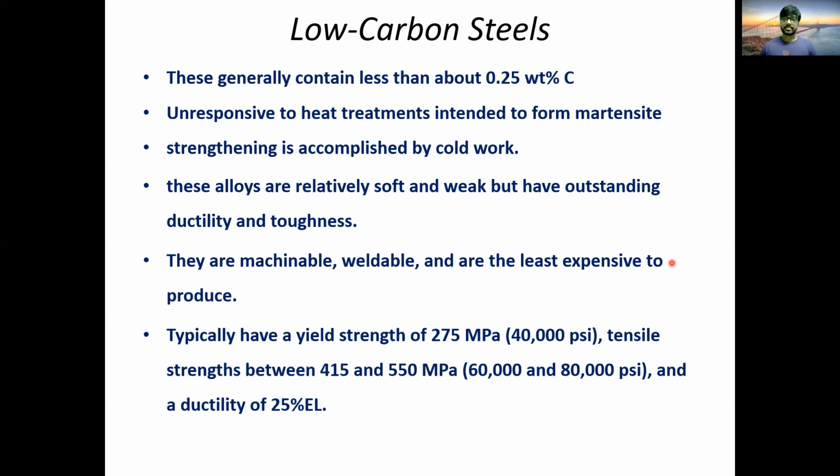They lack hardness, but they are good in ductility. They show good ductile properties. So we have to strengthen low carbon steel for our daily uses. That's why we do some cold work, straining this type of steel.